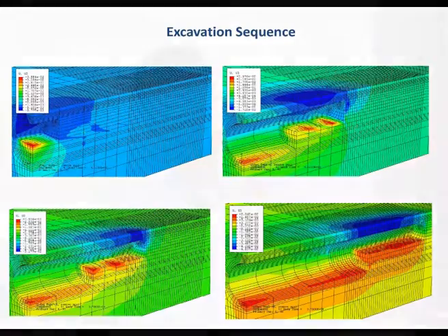Oh yeah, the shotcrete is supposed to take all the displacement. The only thing is that the shotcrete does not have a lifetime of 100 years. You see, the shotcrete is temporary in the sense that if you have a permanent structure, your working life has to be about 100 years or more. The shotcrete doesn't have that working life. So the shotcrete has a shorter working life, and sooner or later, you have to cover it with a permanent lining.